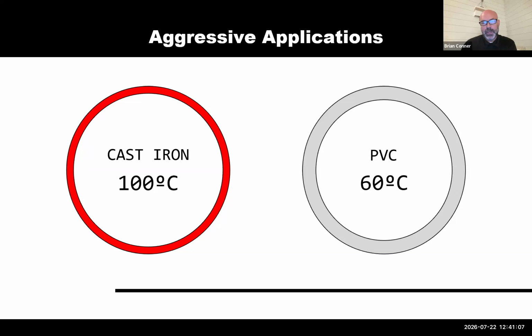increases? You may have noted as engineers over the years that the hanger spacing would decrease on PVC as the temperature increases. And that's a result of the tensile strength decreasing with exposure to hot temperatures. At the maximum working temperature, which is 60 degrees Celsius of PVC, it only contains 22% of its original strength.